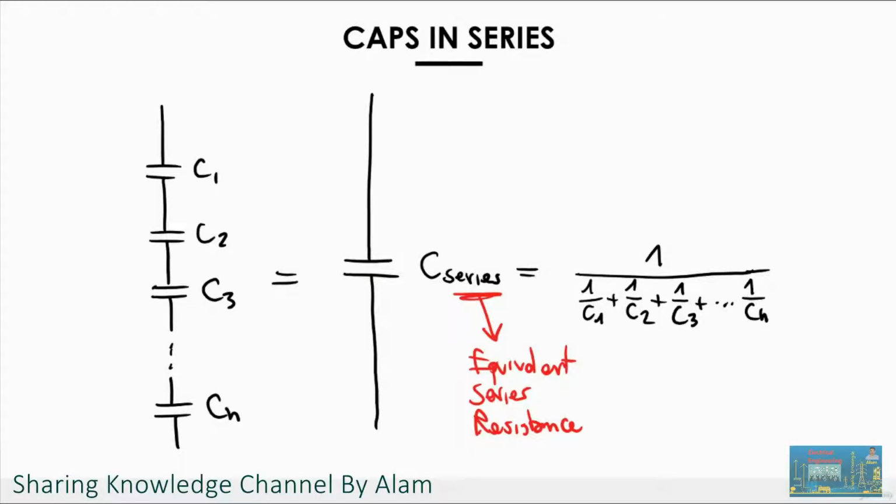Now, if we want to extend the concept, because the example that we've seen before just assumed two capacitors in series with the same value, obviously that's not always the case. In these slides, I'm showing the universal formula that you can use to calculate the series equivalent for capacitors. And you will certainly remember that this formula is very similar to the one for parallel resistors.